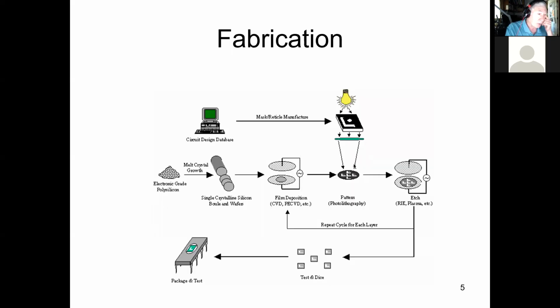All right. So here's how things get fabricated. You basically create the design using English language statements, a hardware description language, and a big integrated development environment. Once you get that all entered, verified and debugged, you basically hit a button, the synthesizer grinds away, and it cranks out all of the photomasks that are used to actually make the chip, because we're still using photolithography for chip production.